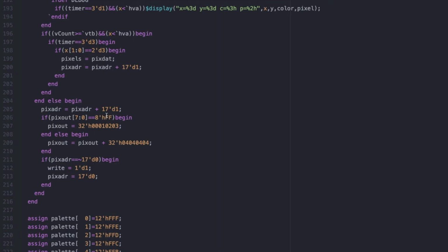Remember, I started it with -1, which is all ones. I know it doesn't sound right, but it's all ones. You add 1 to that, it flips it to all zeros. So there's this little trick. The PLL does a tiny little clock pulse before it's ready to run. It's just setting things up. It does a clock pulse and it watches your incoming clock and then times itself to that. And then it generates a higher or lower frequency depending on how you use the clock wizard. And so I'm eliminating that possibility that I'm starting at a wrong address.